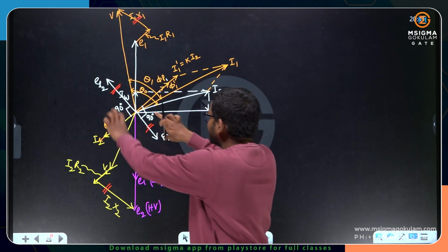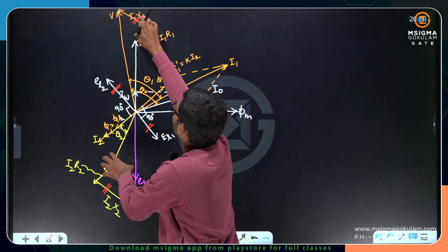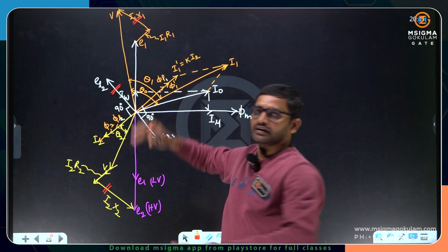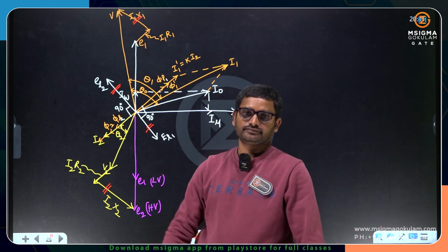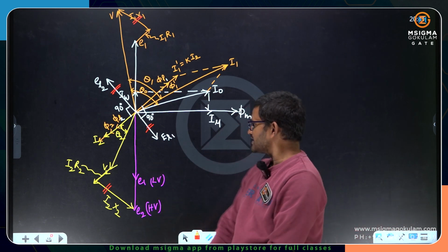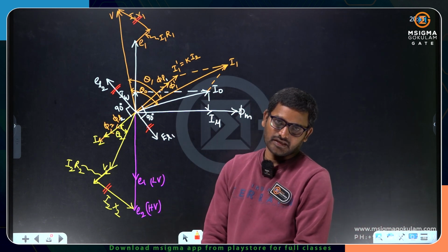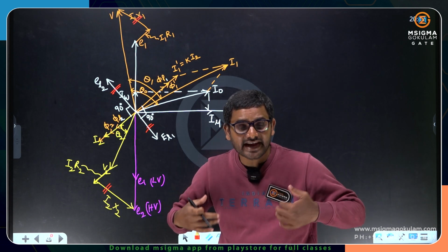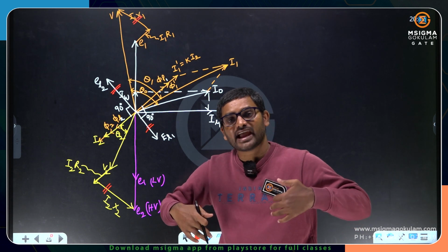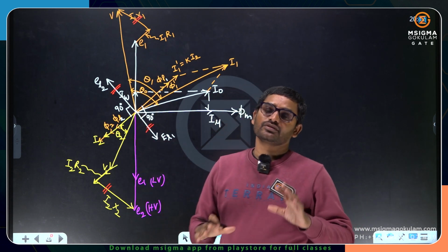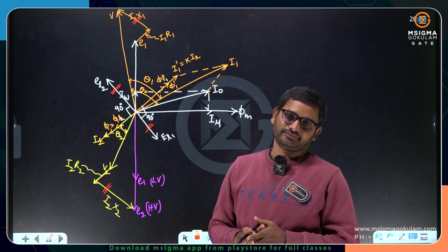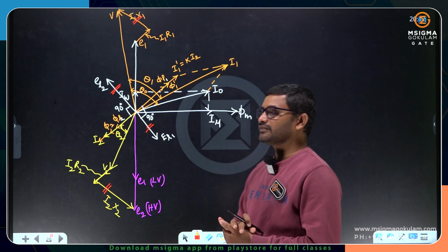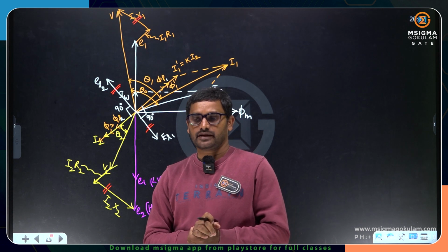And when the leakage EMFs are compensated with the assumed reactances, then you will get again the original phasor diagram. Okay, this is actually the deviated phasor diagram. If X1, X2, whatever the assumed reactances are there, are able to cancel the leakage induced EMFs, then you will not get much deviation. Okay, so this is the actual phasor diagram we can take up.